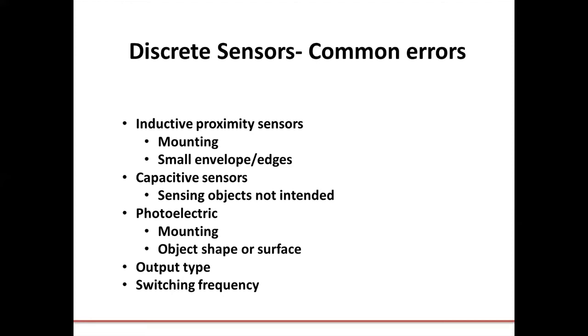For discrete sensors, the most common types are NPN or PNP type, but there are also AC outputs, triac, and relay outputs, many different types. You want to know which type and choose a common type, which is the best practice for proximity sensors along with data acquisition. Normally they're NPN or PNP at 24 volts, but we have modules and hardware which can detect additional types as well. Switching frequency, you also need to be aware of that.